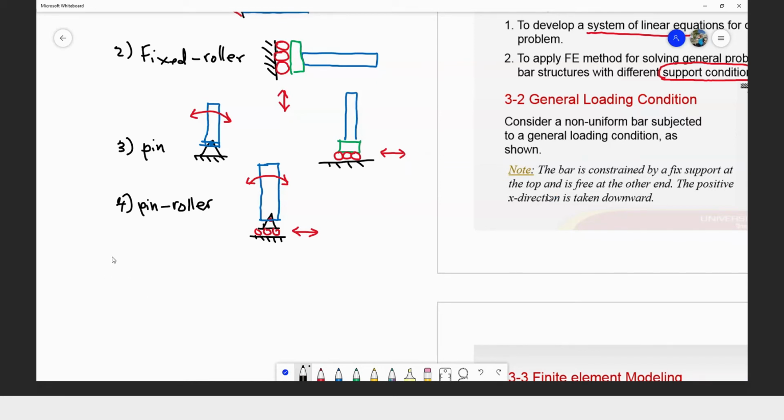So in some cases where the load and the geometry of the structure are symmetry between each other, then we can, macam yang example dalam kita punya meeting sebelum ni, kan, instead of kita modelkan T-junction pipe tu keseluruhan, kita boleh ambil 1/4 saja, and then we apply symmetry boundary condition pada pipe tu.